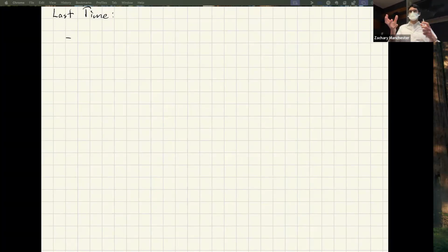This is a good example of the trade-offs between direct and indirect methods. In our context, roughly speaking, a Kalman filter looks sort of like DDP, but it's dual, it's flipped around. In the Kalman filter it's a covariance, and in DDP it's a cost-to-go Hessian. Whereas with collocation, that never shows up explicitly. Instead, you have this big sparse KKT system you factorize. So GTSAM is sort of like collocation, exploiting the sparsity.